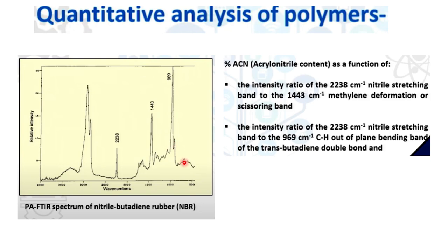So what you will do, you check samples from different suppliers. If there is a variation of acrylonitrile content, you just calibrate the graph. In x-axis you put the concentration of acrylonitrile and in y-axis the intensity. If you check 3-4 known samples and your unknown sample, you will get the data on how much acrylonitrile content is there.